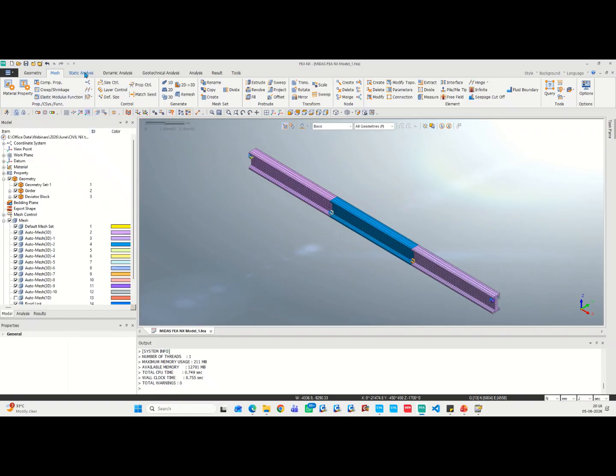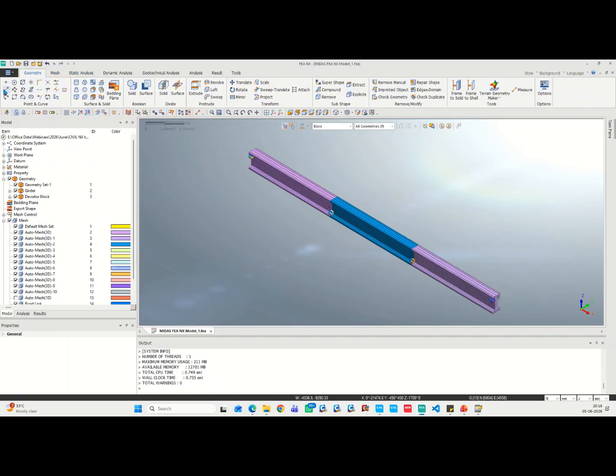To model it, we go to the geometry and create the lines from a particular point where we want to generate the tendon reinforcement, and then use the translate command for assigning this reinforcement. After assigning, make sure that we auto connect the tendon reinforcements.